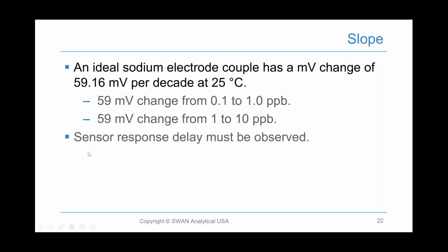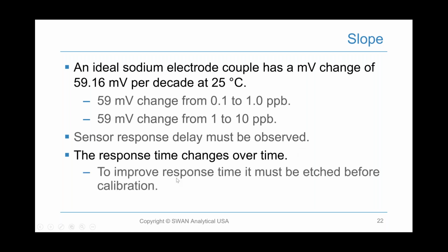You also need to monitor your sensor response delay on a day-to-day basis. That will allow you to determine if the electrode is experiencing the phenomenon called sodium depletion, in which it is slow to respond and is in need of etching to increase that response time. The response time will change over time, particularly when monitoring very low sodium samples. To improve this, it must always be etched before calibration.